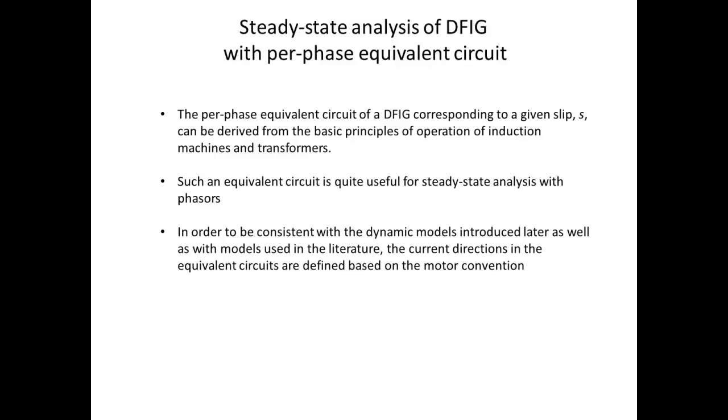So in our generator case, the power would actually be converted from the mechanical side and fed into the electrical grid, and we call that a negative power using the motoring convention. So that is something to keep in mind, and not to be confused when we see a negative value for the grid power. That is because we're using the convention based on the motoring mode.